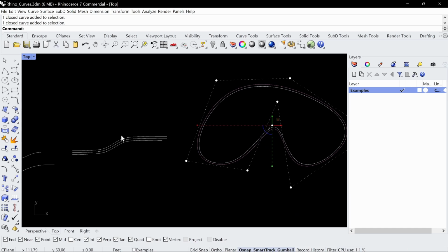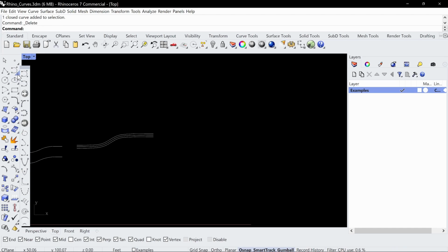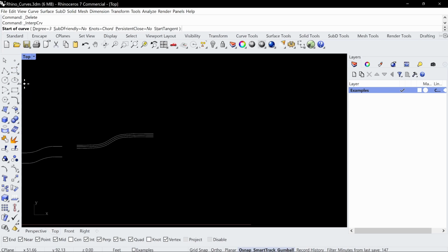If it's a very simple geometry, you really don't have to worry about it, especially if it's very sharp and not curved. But once you start going to curved and bending geometry, make sure that you typically have loose equals no. Now, just to go back again, let me just do the curve interpolate points. I just want to call attention to what degrees can do, both in a curve and in a surface, but we'll just start with a curve. So if I go here, and you see up here it has degree equals 3.